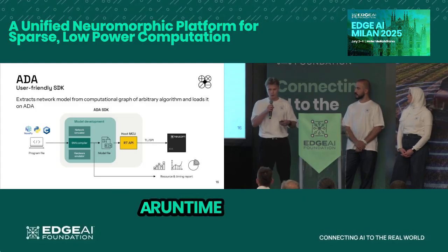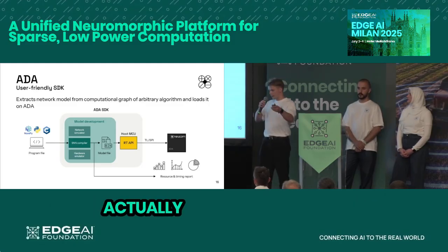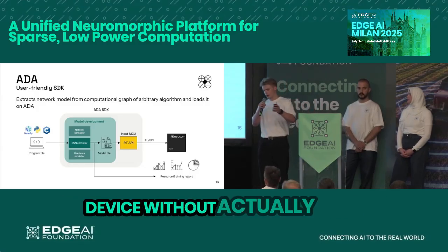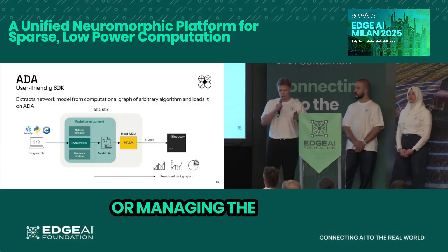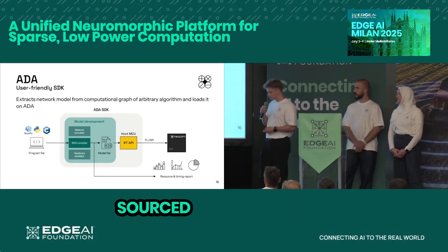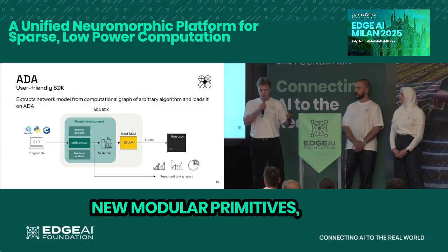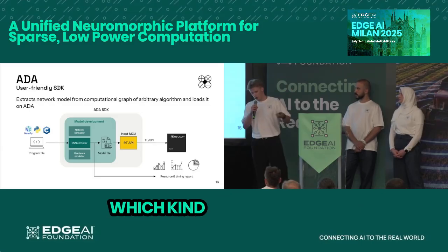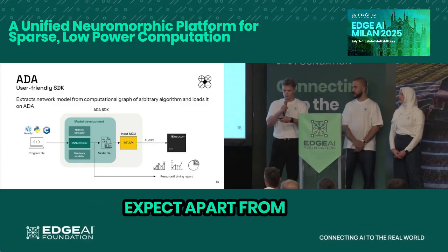This is loaded over a runtime API, which is part of your companion microcontroller. This allows you to move an algorithm all the way to our device without having to interact with any training or managing the network whatsoever. If you wanted to do that, we also provide a network simulator, which is also open sourced. This allows extension or implementation of new modular primitives, one of which we'll introduce in a bit, and a hardware emulator, which gives you an idea of the resource usage and the timing estimates in terms of latency that you can expect, apart from just deploying it on the device.